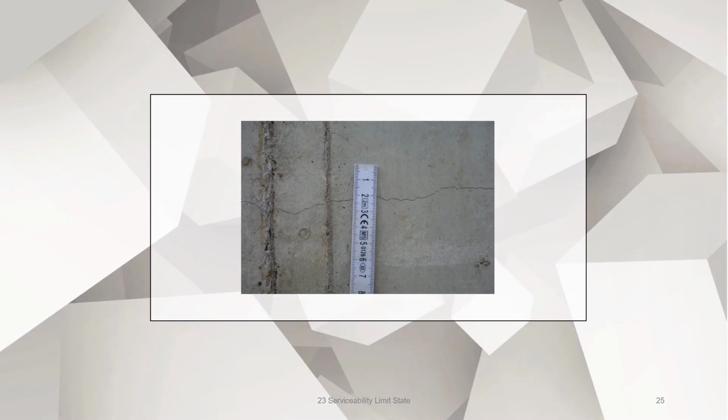You can now estimate the crack width and minimum reinforcement of a concrete cross-section. And remember, increasing the concrete quality has a negative effect on the needed minimum reinforcement. See you at the next lecture.